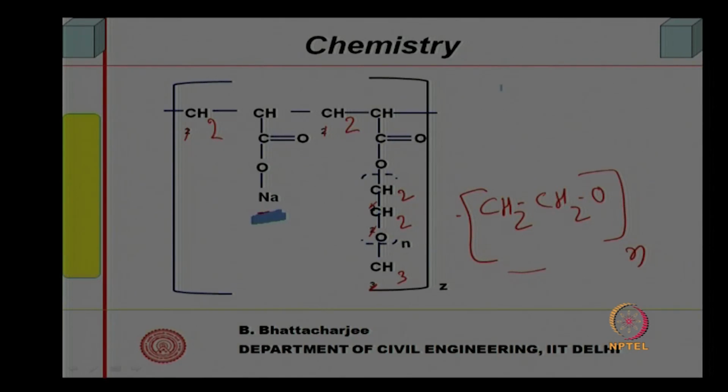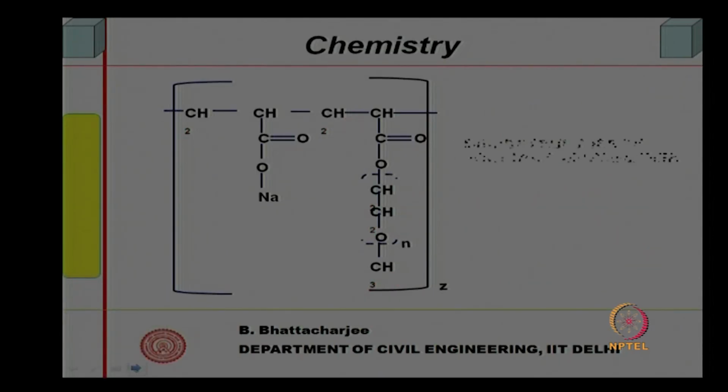So, you have a comb structure, this is the branch which is attached to the cement and something else is protruding out of it. So, this portion is protruding out of it and this is the copolymer. More importantly, you can change this copolymer, it need not be CH2CH2O, ethylene glycol, as we shall see. So, you can have any polymer, copolymer here, any other ether here. So, therefore, by changing this, you can actually tailor make the property of this plasticizer. Let us see how it is done.